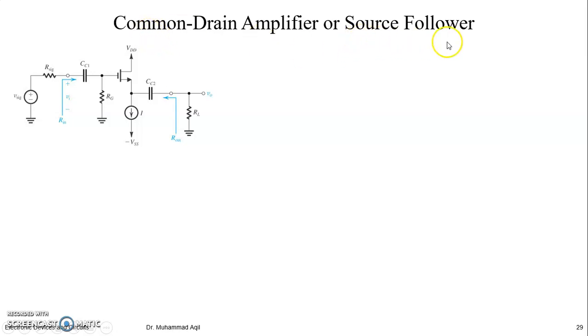So the common drain amplifier, or source follower, right? Here it would be having no RD. The VD is directly coupled to the DC source, and when you want to find the AC equivalent circuit of this signal, then this drain is appearing as ground for the AC signal, similar to what the common collector was. Okay, because the gate is available like the base, it will prefer to be the input port, then the drain has to... the source has to compromise to be the output port.